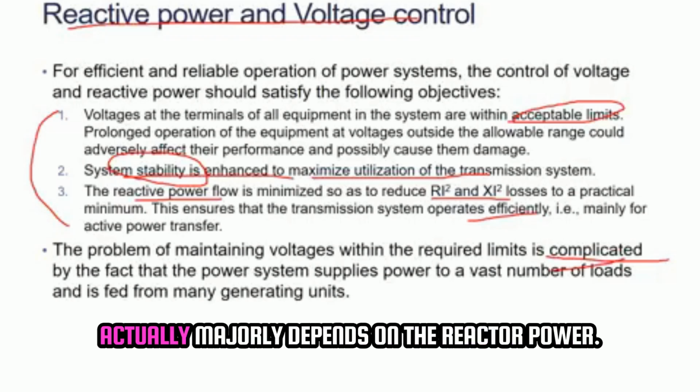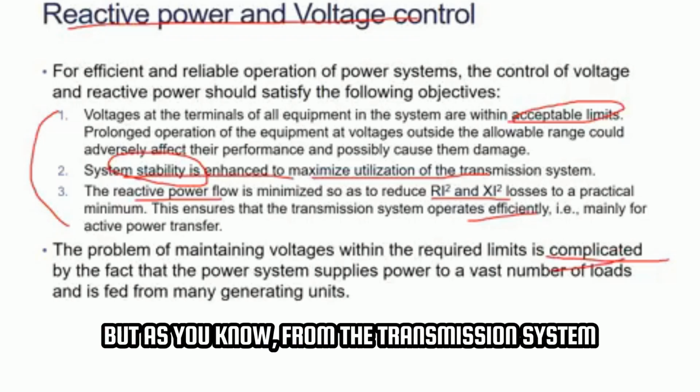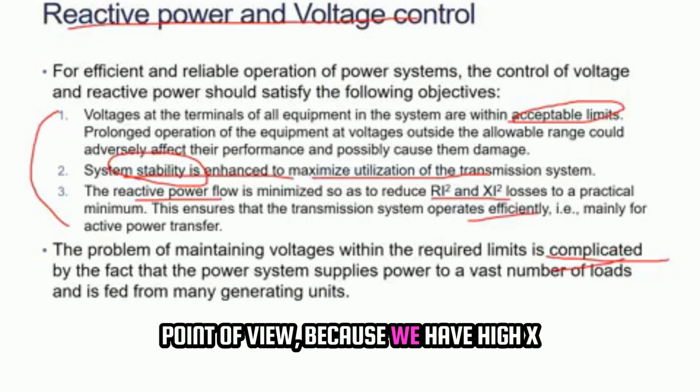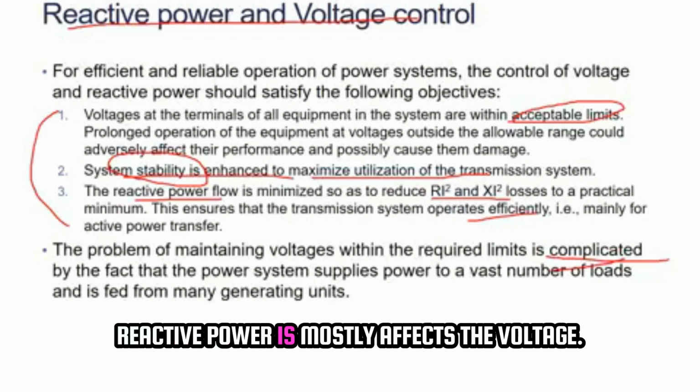And whenever I talk about voltage or reactive power, I'm using them analogously, because voltage majorly depends on the reactive power. Or we cannot generalize it, it also depends on real power, but as you know, from the transmission system point of view, because we have a high X by R ratio, you can easily say that reactive power mostly affects the voltage.